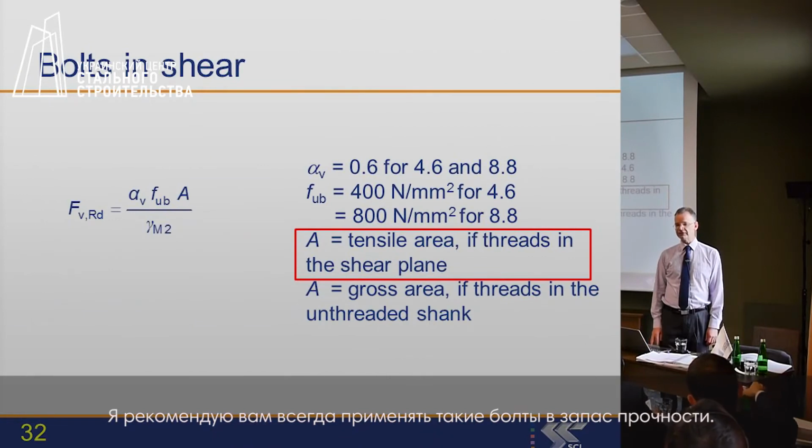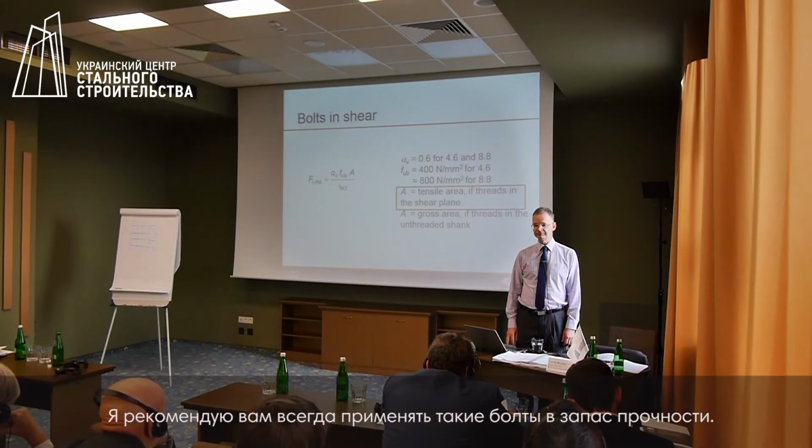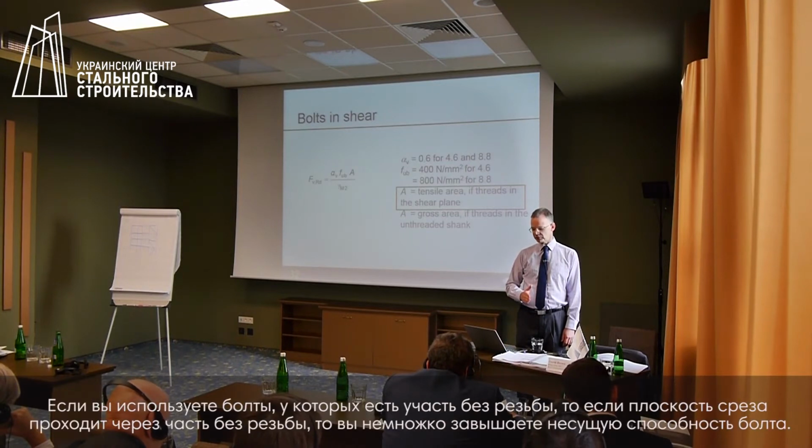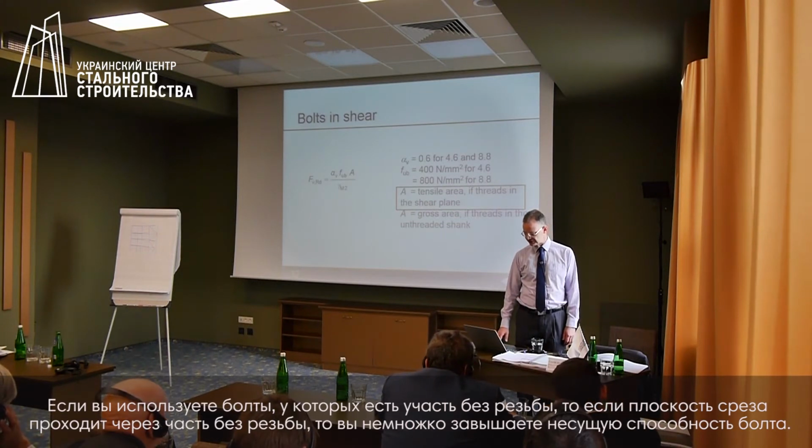If you decide to do that, which I would recommend, you will always be conservative. So if you use bolts which have a length which is not threaded, if the shear plane is in that zone, then you will have a slightly increased resistance.